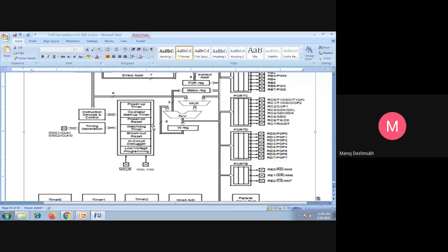Okay, as we have discussed that PIC microcontrollers are working from 2 volt to 5.5 volt, but sometimes there may be a possibility it will reduce the voltage to less than 2 volt, or mostly fluctuations are there. And related to that, if the controller identifies the decrement or reduction in voltage for a specific duration, in that case it will automatically reset your controller so that damage of the controller is avoided.